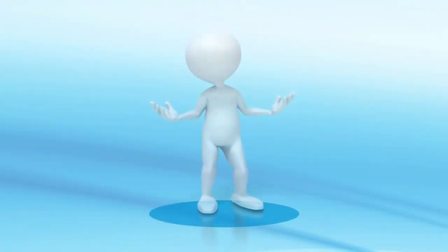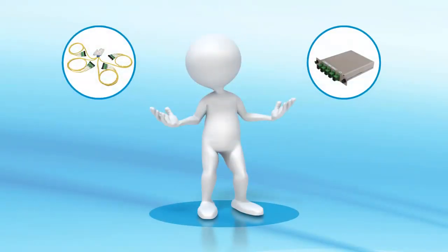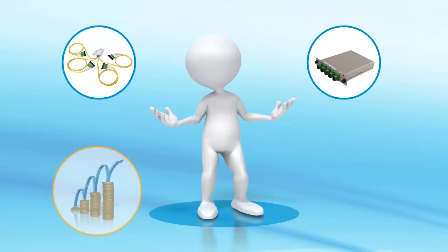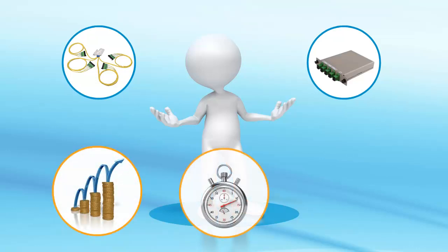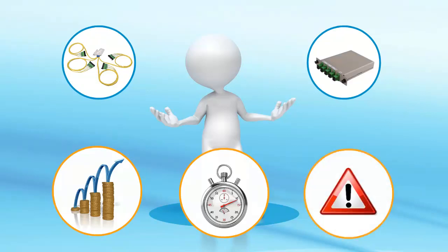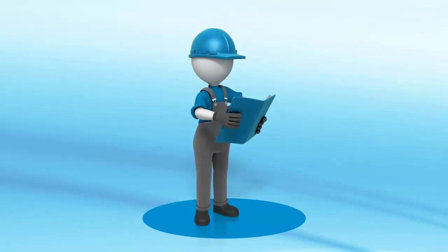Where to locate optical components such as splitters and WDMs has been debated since their introduction. In the past, splitters and WDMs were often housed in splice trays or at the back of termination panels, but putting these components in splice trays increases the cost of installation, the time required to turn up service, and the probability of the device's failure or damage to adjacent fibers. Today, deciding where to house optical components should be based on cable management and network flexibility.